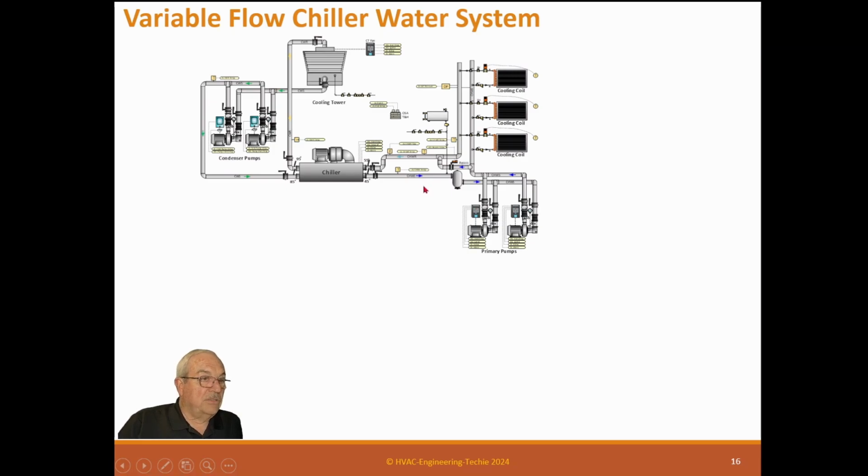It sounds good, in a lab. I'm sure they can set a chiller up and put a really good instrument on that, and they can do that really well. But in practicality in the field, it does not work. And the reason is because things are changeable. If this bundle starts to get fouled at all, the pressures are totally different. Now your flow is totally different.